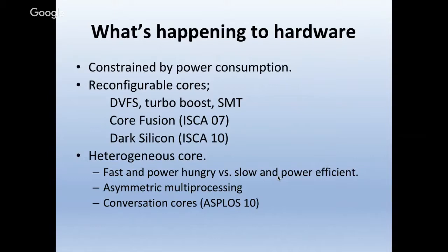On the other hand, the future may have dark silicon, which means we can have many cores, but we cannot power them all at the same time. So what does that mean for us, for adding and removing cores in the system? Well, we already do it today, for example, if a core fails or if we reallocate cores to different machines. On the other hand, you may take cores out of service because we will not power them all at the same time. Also, there are heterogeneous cores in our machine, giving us asymmetric performance. For example, one logical conclusion of this would be conservation cores.